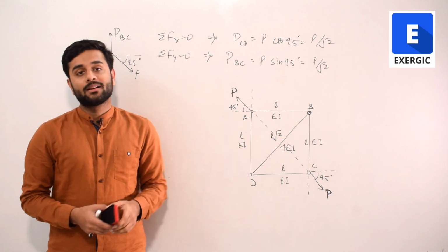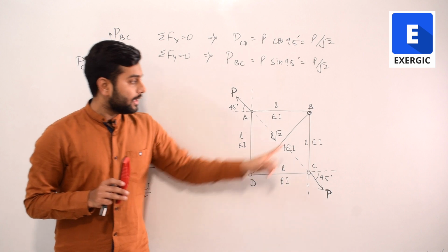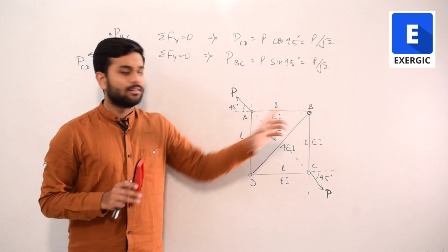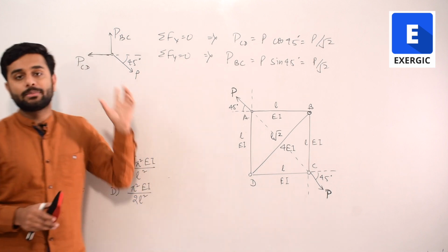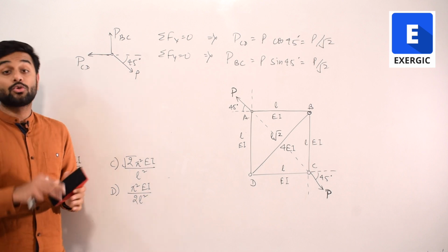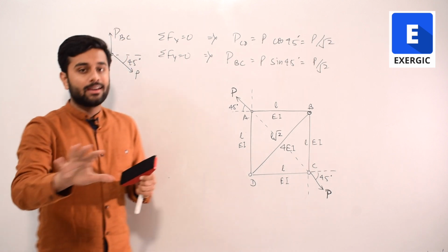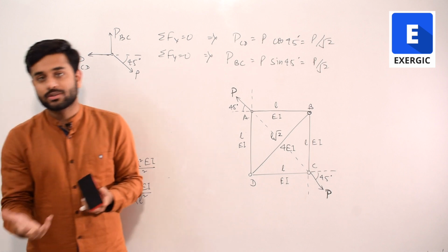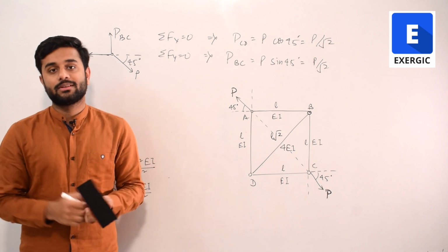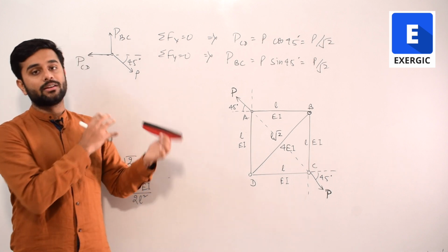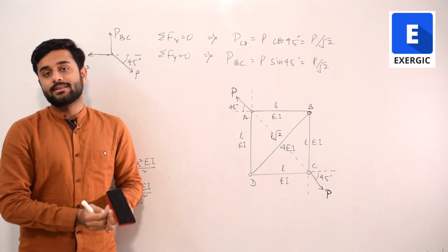But let's pause here and think what type of load is acting in these members of length L, whether it's a tensile or compressive load. Look at it. In the diagram we have represented that to be a tensile load. Now those of you who are getting confused that this force is acting like this, so it will compress BC, they have little weak basics, because I have already covered these silly mistakes, that why some students confuse between tensile and compressive in the FBD of trusses. So if you are falling in that category, you need to brush up your basics a bit.